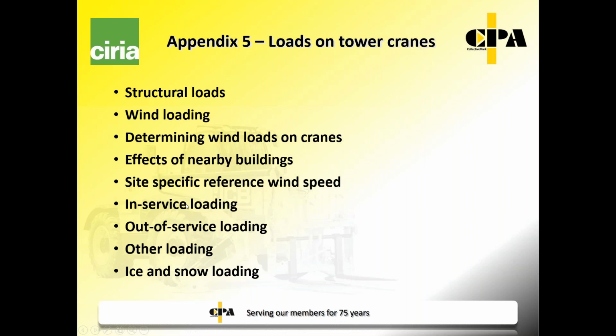Manufacturers will normally provide the in-service loading, the out-of-service loading, and probably the erection loading, because depending on the configuration of the crane, the type of the crane, any one of these may be the highest loading. And so you need to consider all the different types of loads when you are deciding which are the limiting values for design.